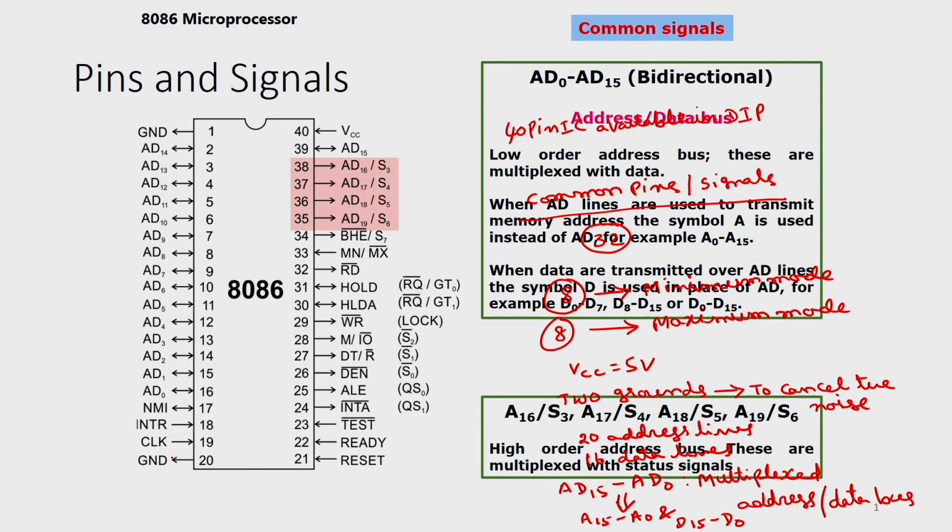We know that the microprocessor requires a 5 megahertz clock in the case of a simple 8086. There are two other versions, which require 8 megahertz and 10 megahertz. This clock has to be generated using an external crystal oscillator. There are different ways to generate a clock signal, such as the Colpitts oscillator and Hartley oscillator, but normally for the microprocessor we use the crystal oscillator because crystal oscillators are more stable.